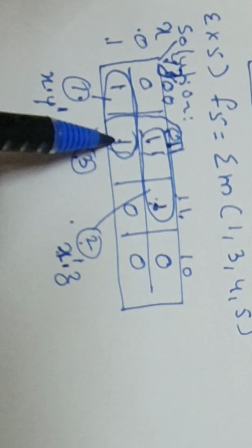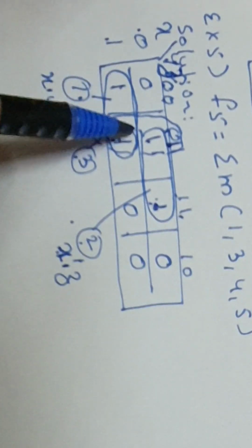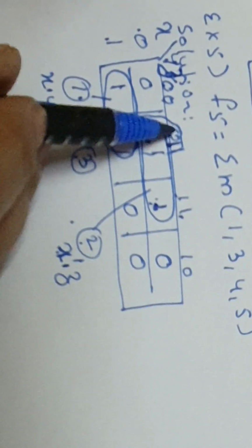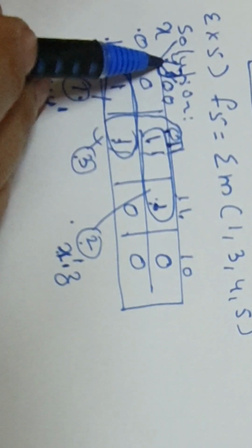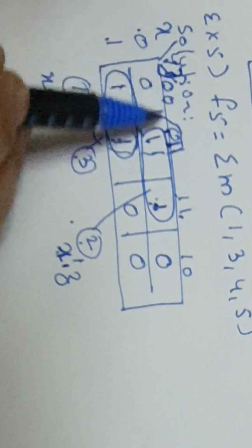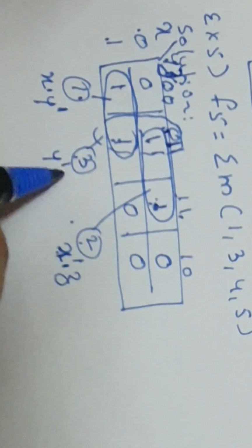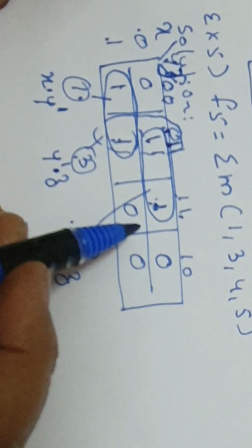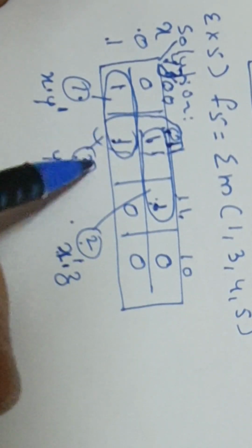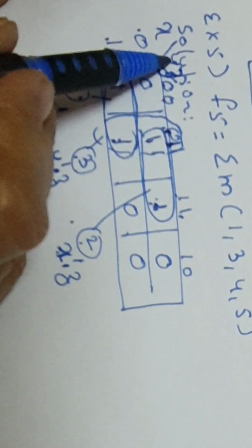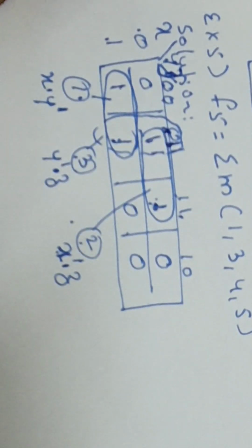For this, these two ones, of course, they make a pair. So they fall in two rows, and row-wise nothing is common. They fall in only one column, and 01 is common. This 0 belongs to Y and this 1 belongs to Z. So Y0 means it is Y dash, and here Z. So 01 is common for both ones of the third group, that is for YZ. So this is Y dash Z, that we have written.